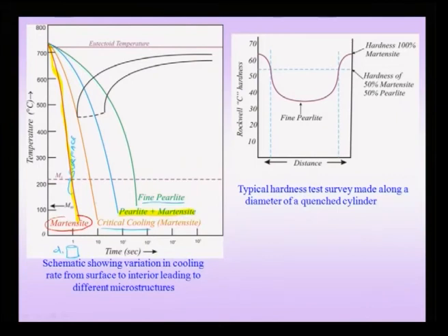So, for critical cooling rate, this will be a diameter D3, and this could be thicker diameters like D4 and D5. So, now we have extended the utility of the CCT diagrams by drawing cooling curves not for different cooling treatments, but for either different diameter cylinders or specimens with different thicknesses, or tracking the cooling at different points within